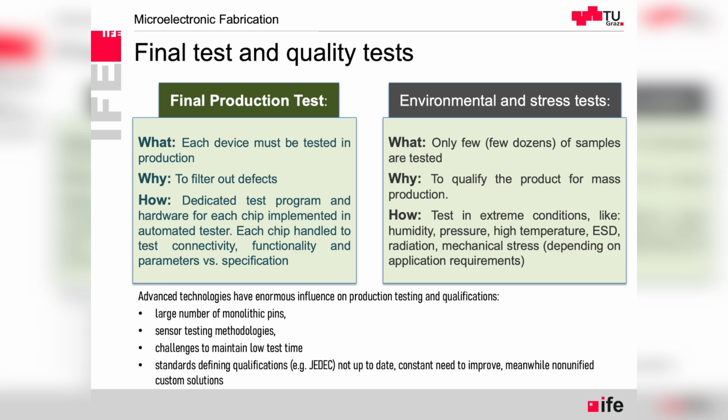For example, in JEDEC standards, there are lots of standards for environmental testing. It describes how many samples have to be tested, in which way, in which operating conditions, how they are then retested to evaluate that everything is still good, and if for such and such environment this chip inside a specific package can be later allowed for.